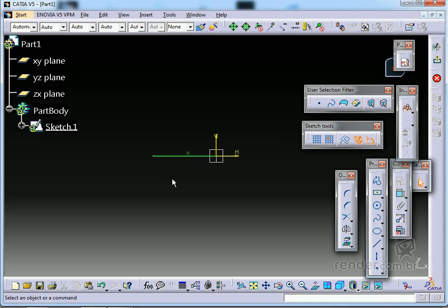But what about the value? No, CATIA works with parameterization, so I create the line and then I come up with this constraint option. If I click, I'll go on the line. I don't need to take it from end to end. I just take the line, click it, move up with the mouse to the distance you want. It's just a sketch, you don't have to leave everything tidy. Once this is done, just click with the mouse and the line will remain.